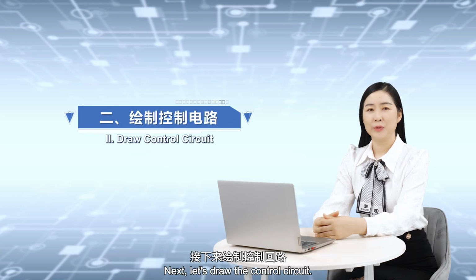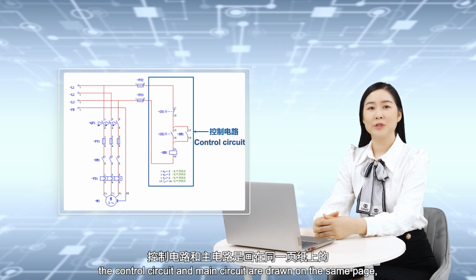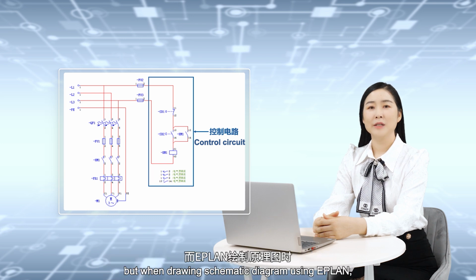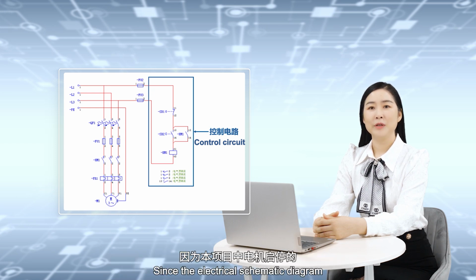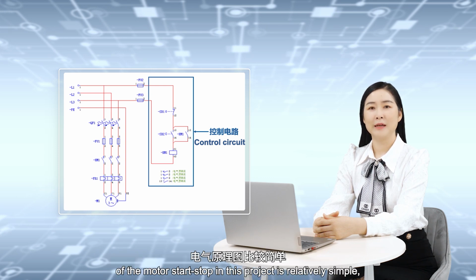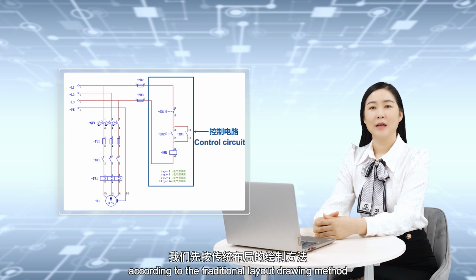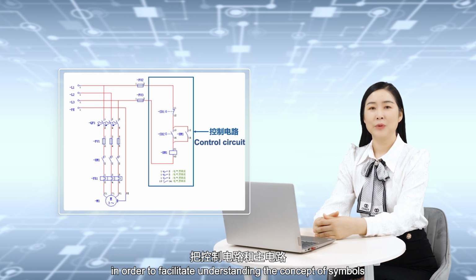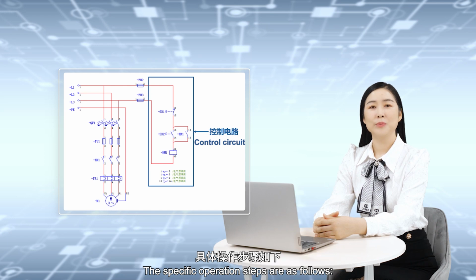Next, let's draw the control circuit. In a traditional electrical schematic diagram, the control circuit and main circuit are drawn on the same page. But when drawing schematic diagram using ePlan, the control circuit and main circuit are drawn separately on 2 pages. Since the electrical schematic diagram of the motor start-stop in this project is relatively simple, we first draw the control circuit and main circuit on the same page according to the traditional layout drawing method in order to facilitate understanding the concept of symbols and automatic wire generation. The specific operation steps are as follows.